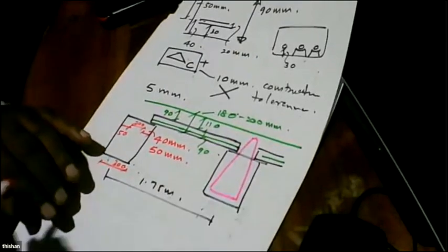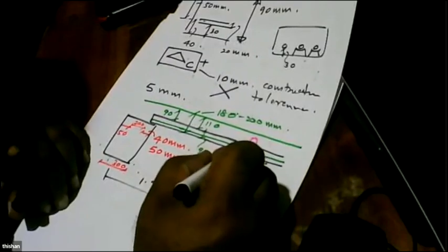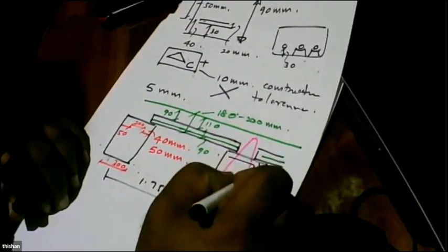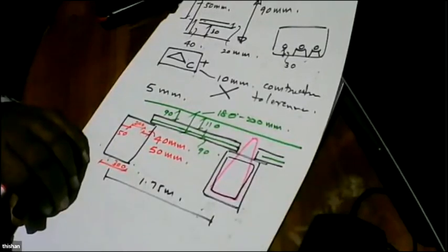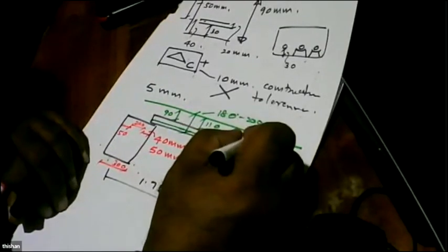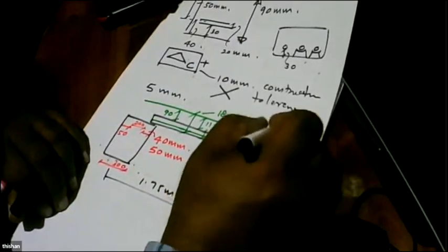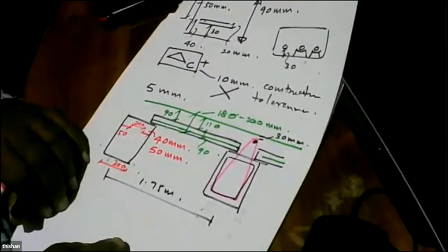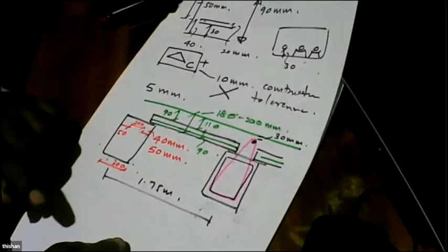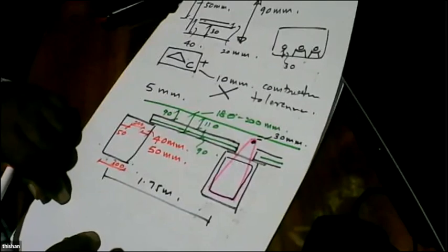This is one link, and when you are casting, you can even have another link like this. The idea of this link is it should go up, and we have to have 30 millimeter cover at this end. We can easily ensure 30 millimeter, so if you want, you can go for 35 millimeter there also.